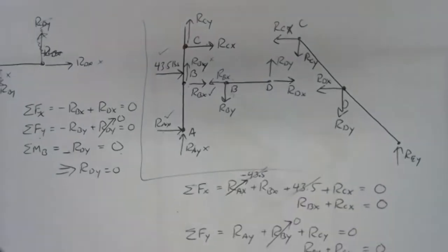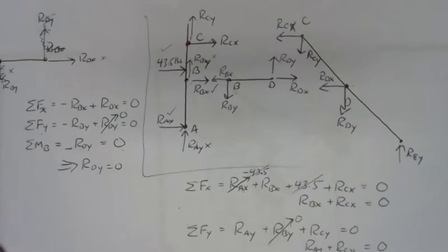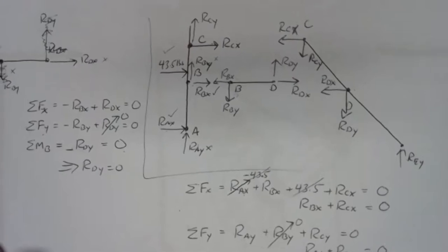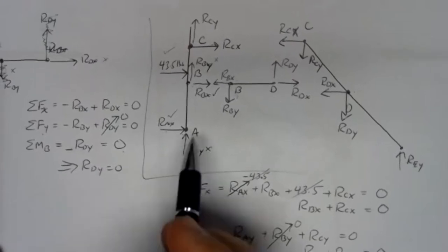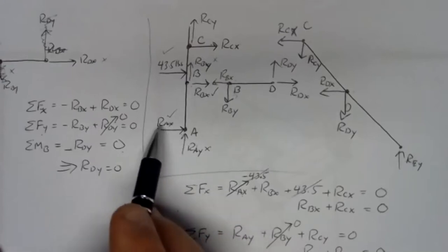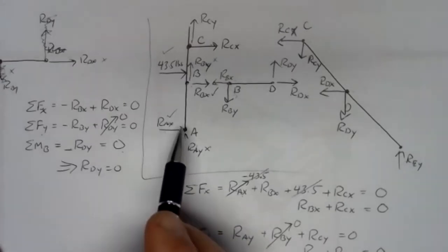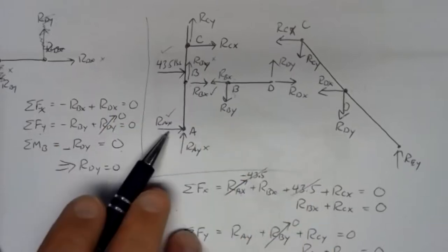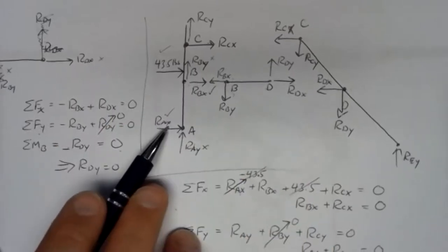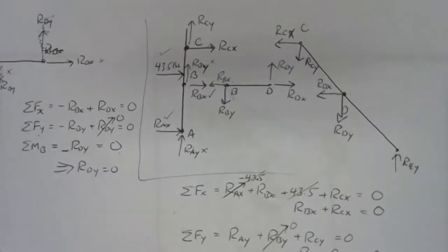And to avoid problems with negatives, it's best to work these equations symbolically and then substitute in what you got from your equations or from your table. If you try to work in negatives here, you run the risk of flipping the arrow and then losing the negative or adding an extra negative in. Work it out using the symbols and the arrows and the assumptions you made, and then plug in the numbers from your table. You'll avoid making sign errors that way.